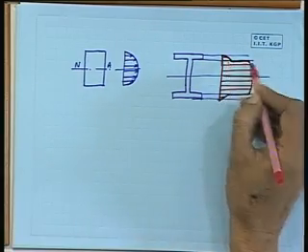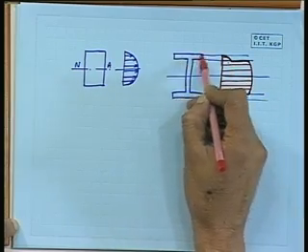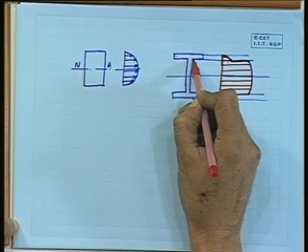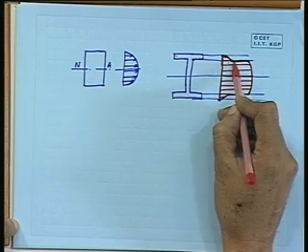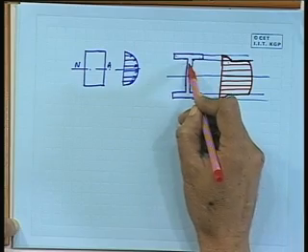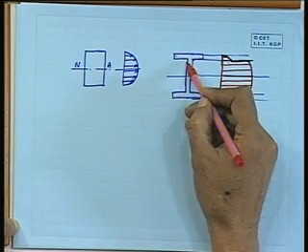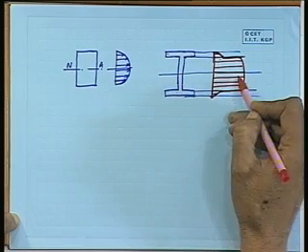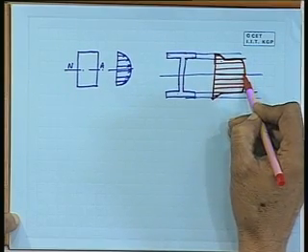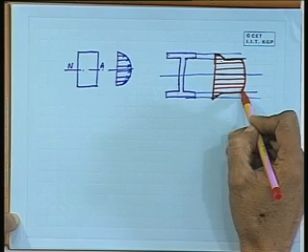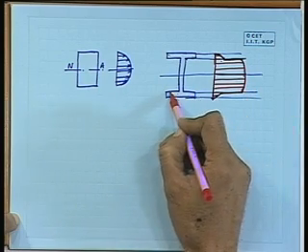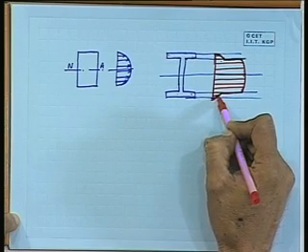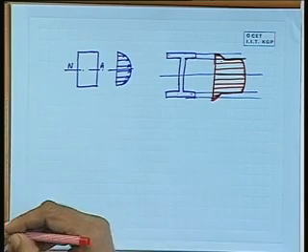So this is a part of a parabola here, because this is also a rectangular section. It's just a part of a parabola, but the width is very high. Then suddenly the width decreases here, so it shoots up. And then this is constant. So the area moment, or moment of this area, does not increase much. It becomes maximum here, and then it drops down to this side. And then suddenly the thickness changes and there is a sharp drop here, and then once again it follows a parabolic path.